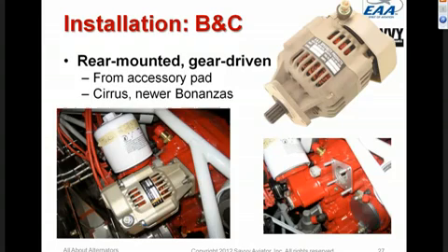And very much like a vacuum pump, it has a frangible plastic coupling that will shear if something bad happens to the alternator, in order to protect the drive gears in the engine.